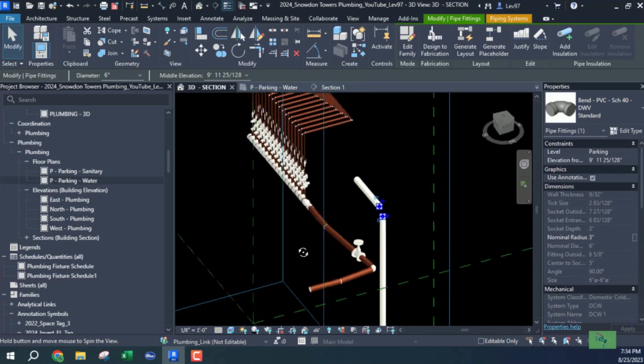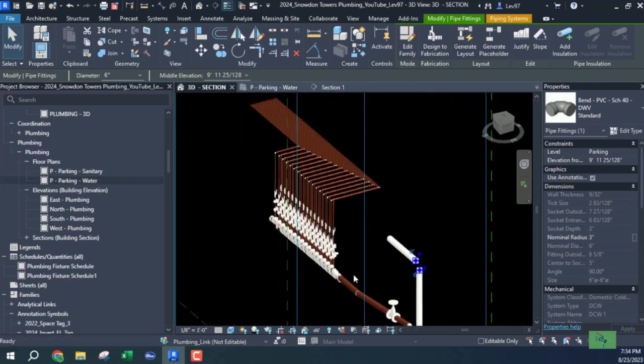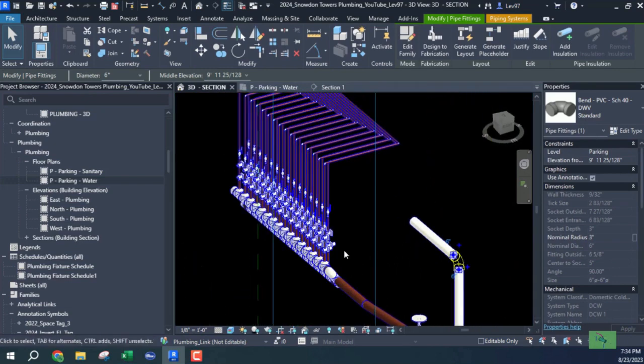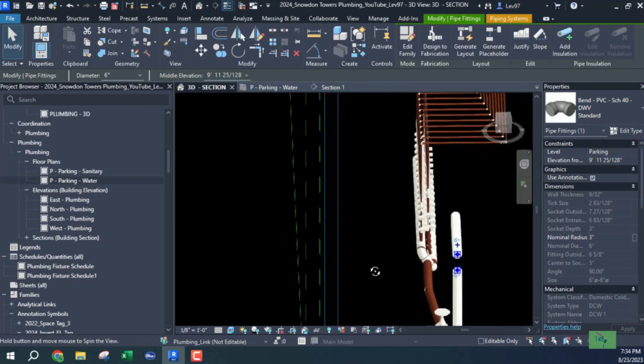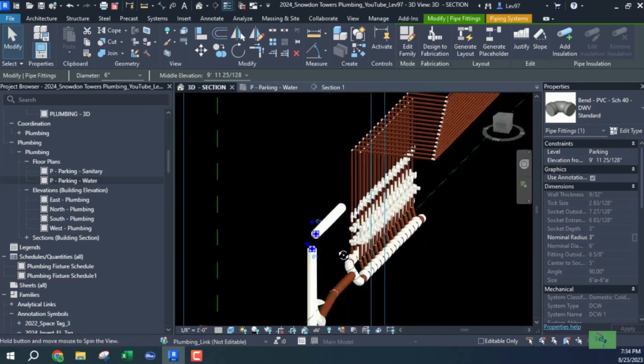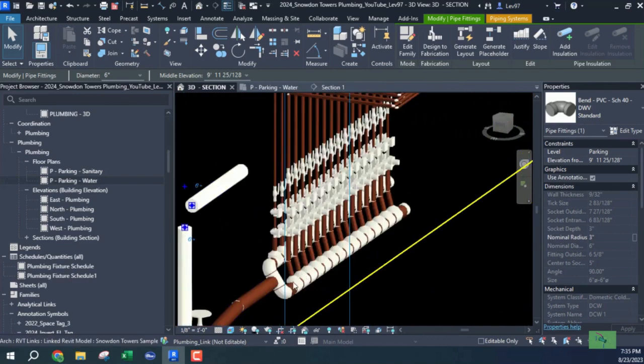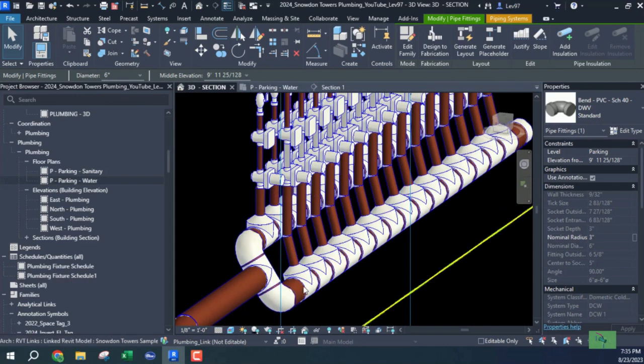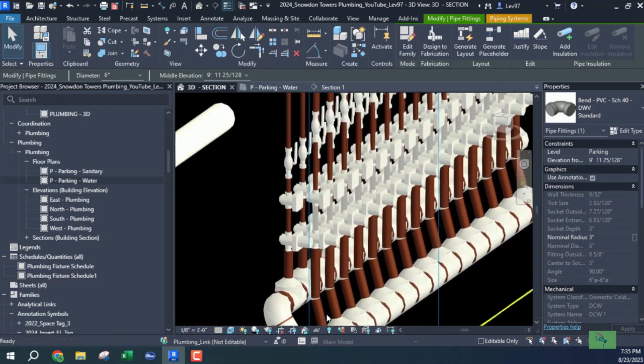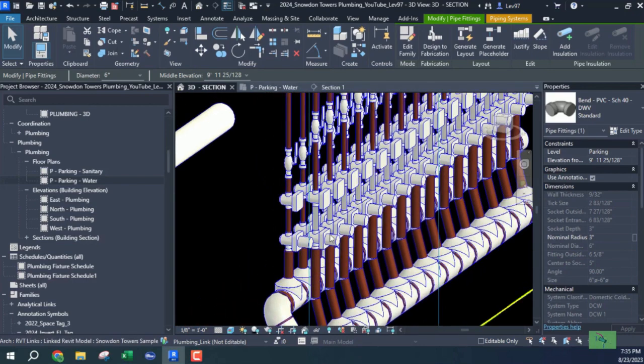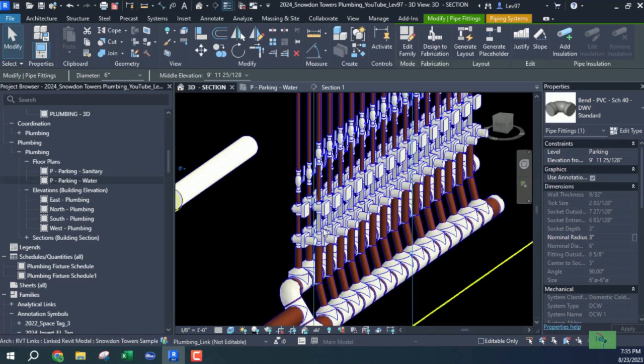So what we need to do is bring in a 6-inch and somehow have some type of a manifold so that each one of these, I can take off from the 6-inch to a 2-inch, and then from the 2-inch, put in all of these regulators.